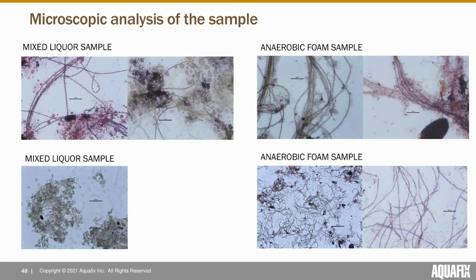In addition to the filaments, they also were having issues with loading going disproportionately into their digesters. They were loading one of the digesters that was foaming with a lot more solids than they were intending. They had two digesters side by side, and one of them was getting more foam than the other. They both were foaming somewhat, which indicates the filaments were a major player to some extent. So good job to people who thought the filaments were a contributor here.